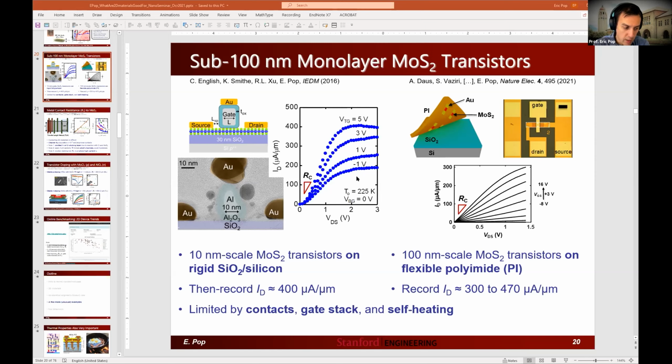We have looked at boron nitride as a gate insulator, but the problem with boron nitride is it has an even lower dielectric constant than aluminum oxide. So boron nitride, in my opinion, is not a good choice for gate dielectrics. Maybe a single layer of boron nitride may be good just for the interface, but then you have to follow that up with a few nanometers of something like hafnium oxide or zirconium oxide, or if you're aware of it, some 2D dielectric that has a high K. And by high K, I mean more than 15 or 20 relative K.